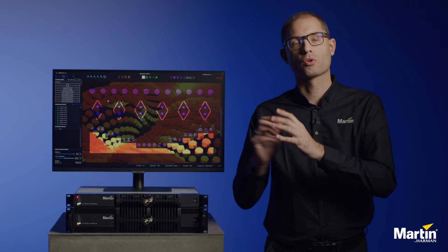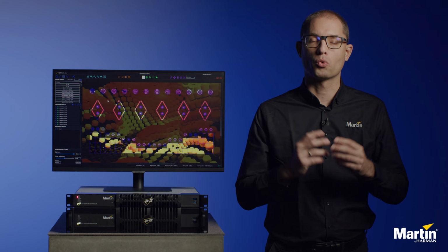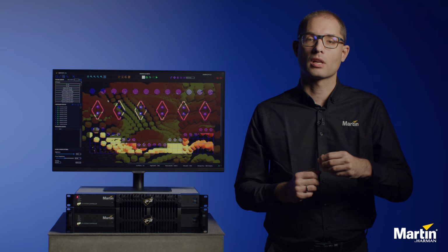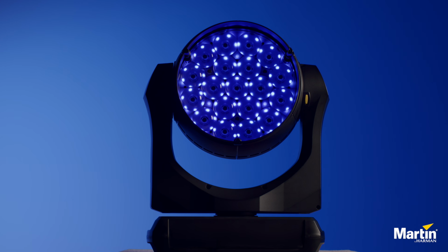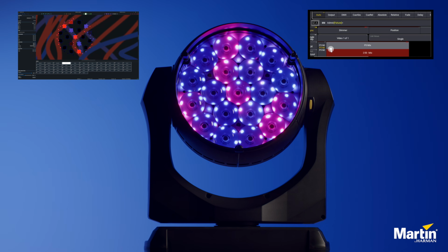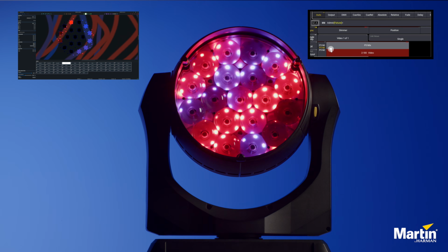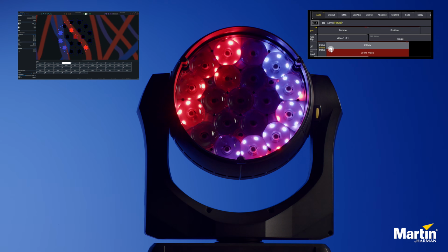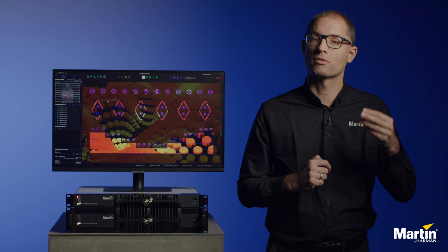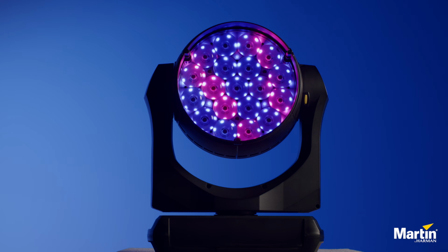Once fixtures are mapped onto the video workspace and patched to the lighting console, you can create looks the way you want. On fixtures like the Mac RPXL, the P3 Mix channel allows you to crossfade between the looks created on the lighting console and video mapping on the incoming HDMI or NDI feed. This always gives individual pixel effects, regardless of the DMX mode the fixture is set to. In many cases, this allows you to set the fixture in a mode with fewer channels and achieve a massive saver on console parameters.